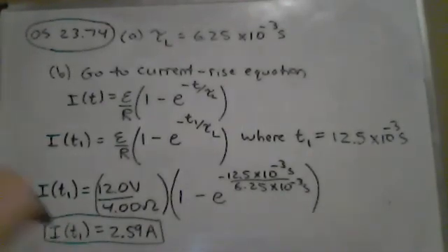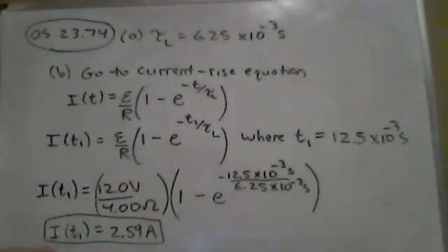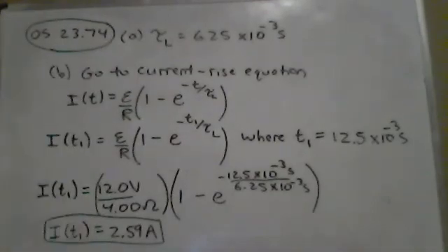So that means that in two time constants, your current is at 86% of its maximum, right? And so at that point, you're pretty well along your way. The maximum current is clearly going to be 12 over 4. If I didn't have the inductor there and I just turned this current on, it would go right to 3 amperes very, very quickly. Whereas the inductor slows it down, so it takes 3-ish, or a little more time constants to get to a more or less fully developed maximum current. All right, so that is all I have for chapter 22.